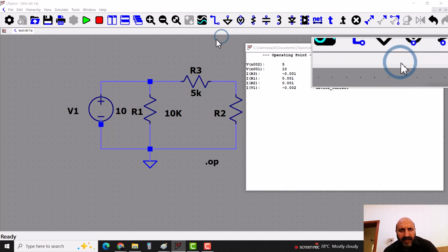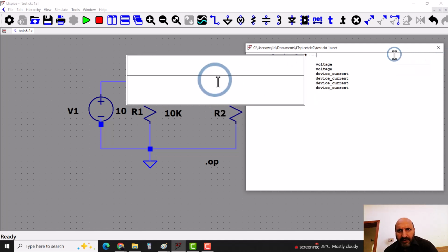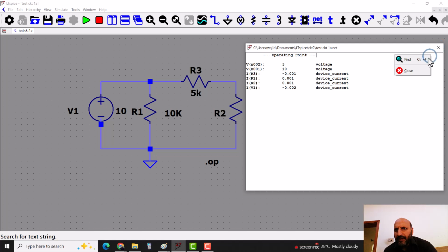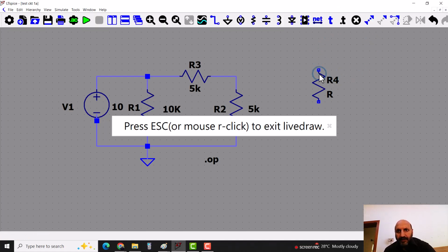So if I grab this resistor here, okay, I have to leave this. I'll first go out from the zoom and close. And the problem in that simulation was due to this particular reason, that if I grab a resistor here and right click, the PSpice by default assumes that this is plus, this is minus, and the current is flowing here.